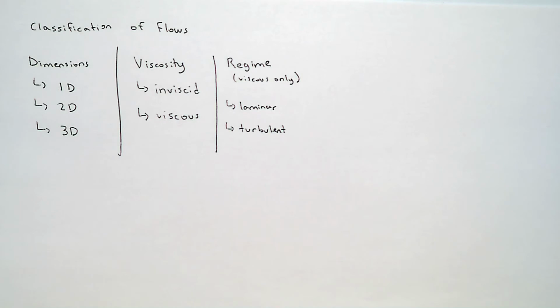But essentially, when I do fix the link, you'll see he essentially mixes two different food coloring dyes, but he maintains the flow regime laminar. And what does that mean? Since flow does not travel from one layer to another, when he brings the flow back, it essentially reverses the colors and the dyes return to their original colors. And that's what laminar flow is. It's flow that doesn't mix because it does not travel from one layer to the other, and therefore it is reversible. Turbulent flow is different.